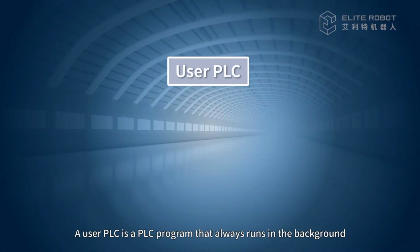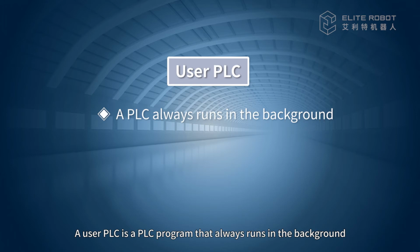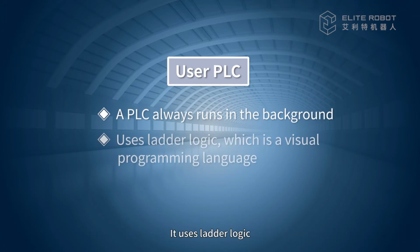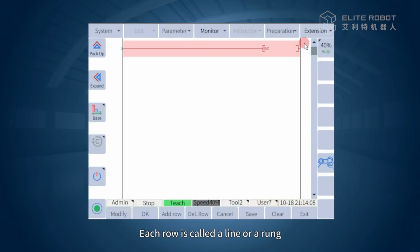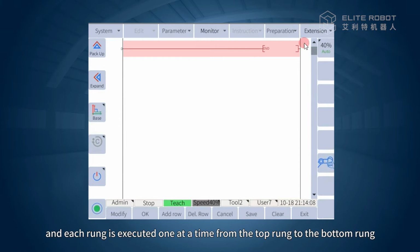A user PLC is a PLC program that always runs in the background. It uses ladder logic, which is a visual programming language. Each row is called a line or a rung, and each rung is executed one at a time from the top rung to the bottom rung.